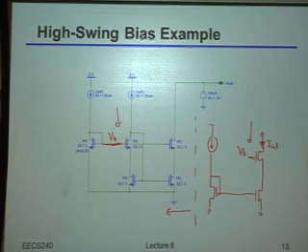Okay? Now notice, if I'm doing a current mirror, indeed, I'm trying to get two things to match each other. I'm trying to get, for example, the current in this branch right there to be some multiple of the current in that branch. Okay? So why is it that I claim that what I did in this left-hand picture is really much, much better than what I did in the right-hand picture? I think it's because the drain voltage on M1 is shielded, so it's more likely to actually match the drain voltage on M3. Yeah, exactly.